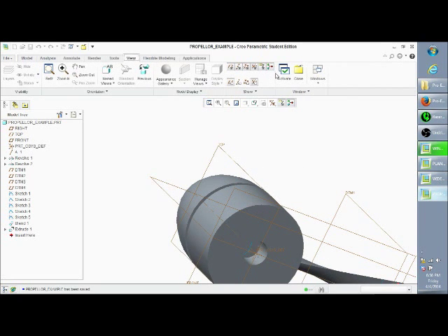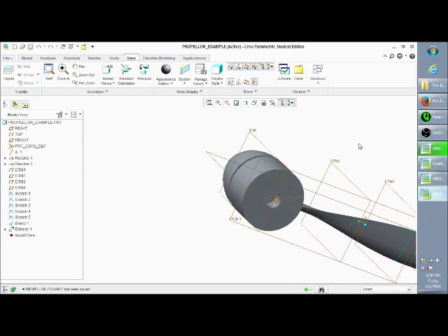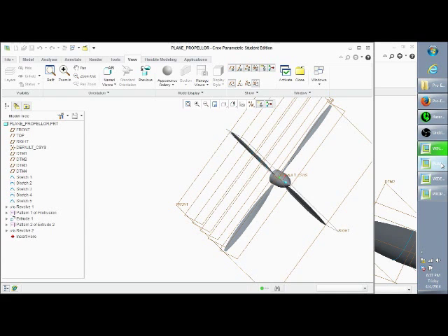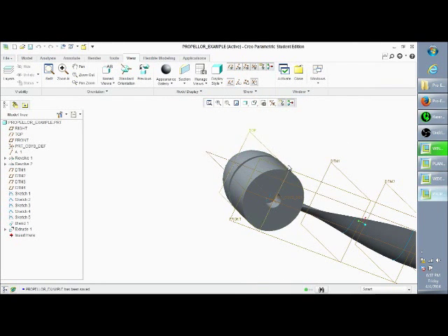I'm going to activate it, View, Activate. If you don't know what the activation button does, if you're flipping between parts, it activates whatever part you were in last. So if you open up a part from a fresh new part, whatever part you open up will be your recently active part. But if, like I've been doing, I wanted to go to this view, I need to activate it before I can do anything within this window, because I'm still technically within this part, messing around within here.